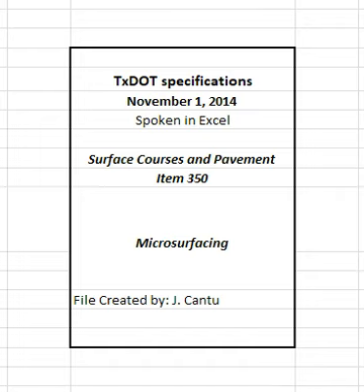Table 1. Master gradation limits. Percent passing by weight or volume. Sieve size and percent passing. Sieve size 3/8 with 100% passing. Sieve size number 4 with 86.0 to 94% passing. Sieve size number 8 with 45.0 to 65% passing. Sieve size number 16 with 25.0 to 46% passing. Sieve size number 30 with 15.0 to 35% passing.